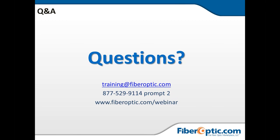In fact, I was just out on a job today where I was using a power meter to troubleshoot an issue in a building. We're always going to use power meter, light source, ORL testing, and ORL tests can be done with your OTDR. So power meter, light source, and OTDR, those are your big, workaday tools.